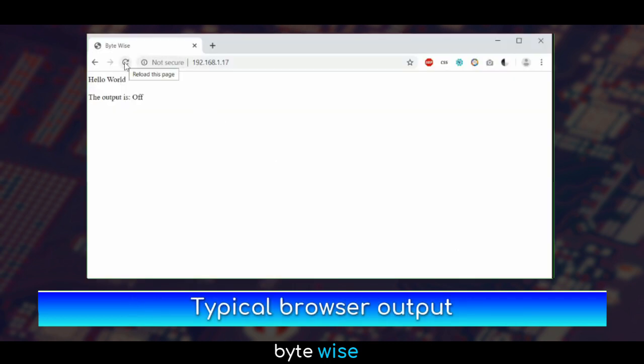Using the IP address noted earlier, we can now test the changes, downloading them to the board in flash mode as before. The page responds to manually changing the output, although as written here, it can only show changes to the output when the page is manually refreshed. It also seems relatively slow, which is probably because the whole page is fetched on each refresh.